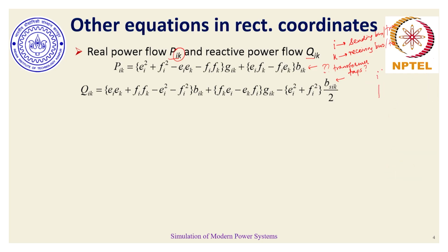If I have bus I and bus K, with a transformer having the corresponding leakage admittance marked as yik of the transformer, and the tap is at the bus K side, then with reference to the earlier transformer tap discussion, you would easily see that we had written the expressions of Ii and Ik.